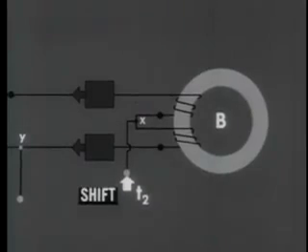As we saw before, this current goes to point X, where it divides, and the branch currents enter the two halves of the split winding. The upper branch current comes out on the non-dot side of its half of the split winding. The lower branch comes out on the dot side of its half of the winding. And both of them move along to the diodes.